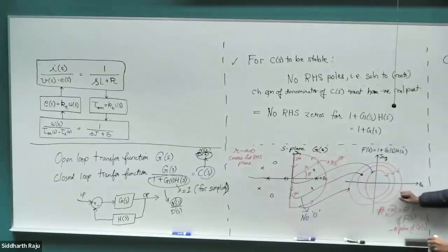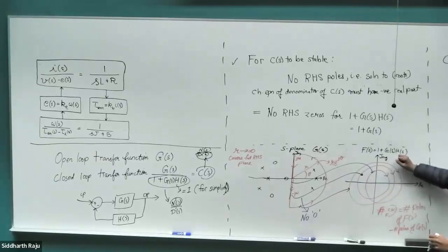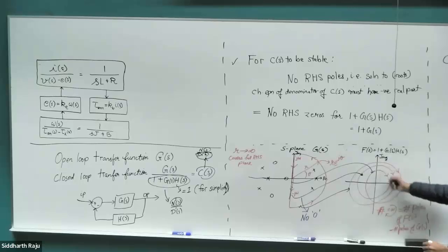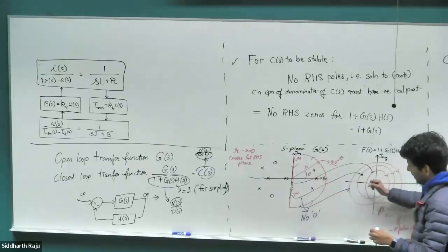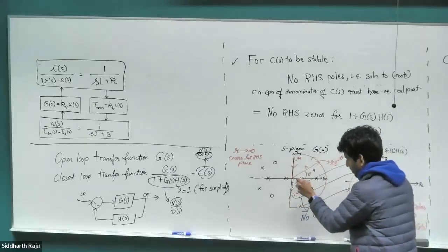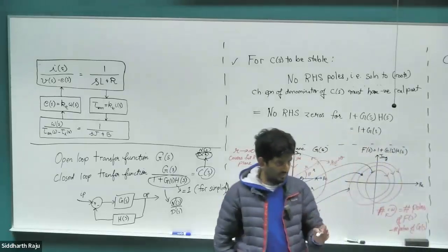And then once we go to the Nyquist domain, in the frequency domain, and map each of those single points, we see that it will encircle the origin in the anti-clockwise direction. And the number of times it encircles must be exactly equal to the number of poles we identified here. Even if it's one less, that means a zero has snuck in here. Right? That will be problematic because the system is now unstable.